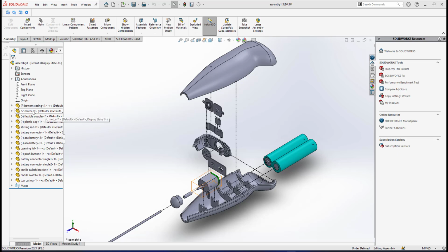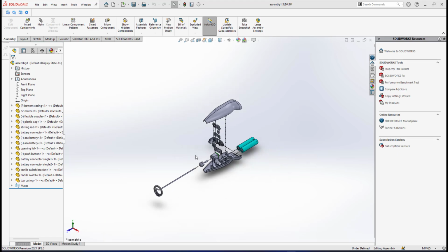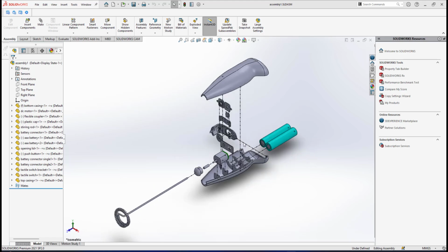Since I've finished putting all these components into hierarchical order, now I will show you how I do the assembly drawing and also the exploded view drawing. Let me save my file first. In order to do the assembly drawing and exploded view drawing of this Milk Frother, I will click this arrow at New, then go for Make Drawing from Part/Assembly.